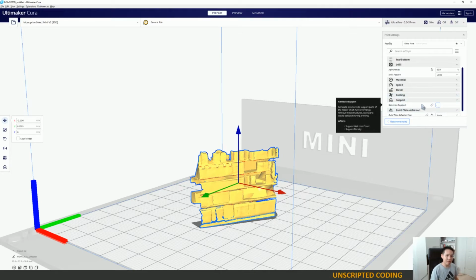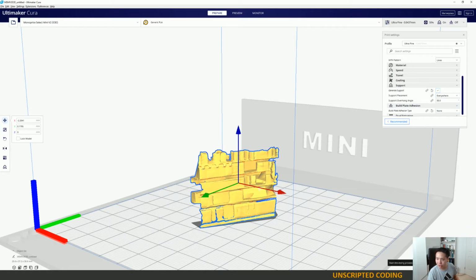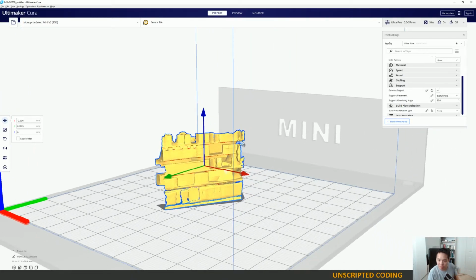So I don't know if you guys do a lot of 3D printing, but you can't just print in midair. The idea is you print one layer at a time, and probably the best way to do this is to show, to actually slice this model ready for printing. But if you are printing one layer at a time, you can't just print in midair, and some of these pieces basically start in the middle of nowhere. And so what you want to do is print the supports, and you'll rip off the supports afterwards.